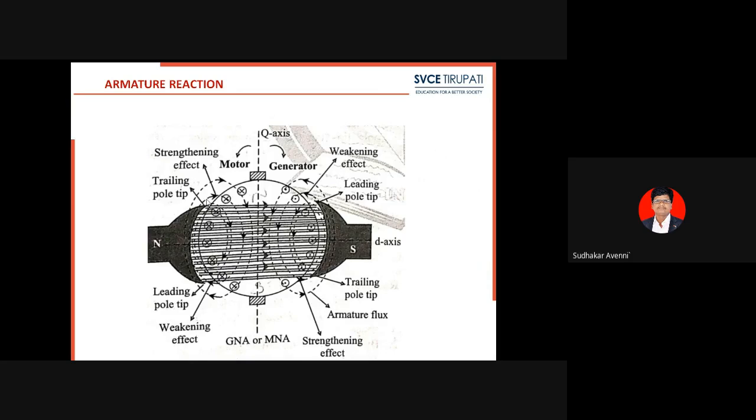So for that we find this is the direction of rotation of the armature flux under the north pole conductors. Similarly, under the south pole conductors, current is leaving. According to Fleming's right hand thumb rule, the curled fingers represent armature flux direction and the thumb represents current direction. For that we identify these as the directions of armature flux.